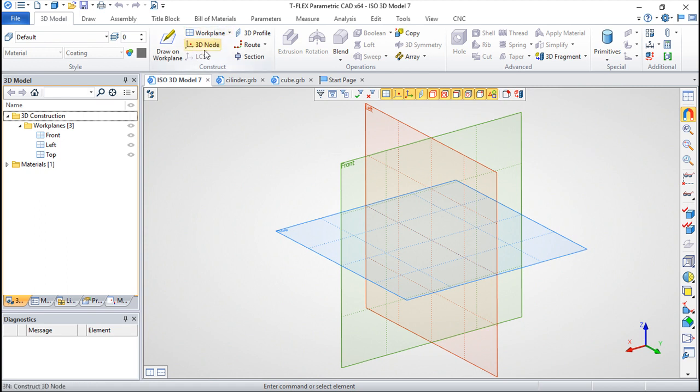So to create the assembly, I will use first the method which I think it is more convenient in the majority of occasions. It is the bottom-up concept, which is to be used by the insertion of parts that you have already in files, and you work in those parts in separated files. So you will insert those files in your assembly context.